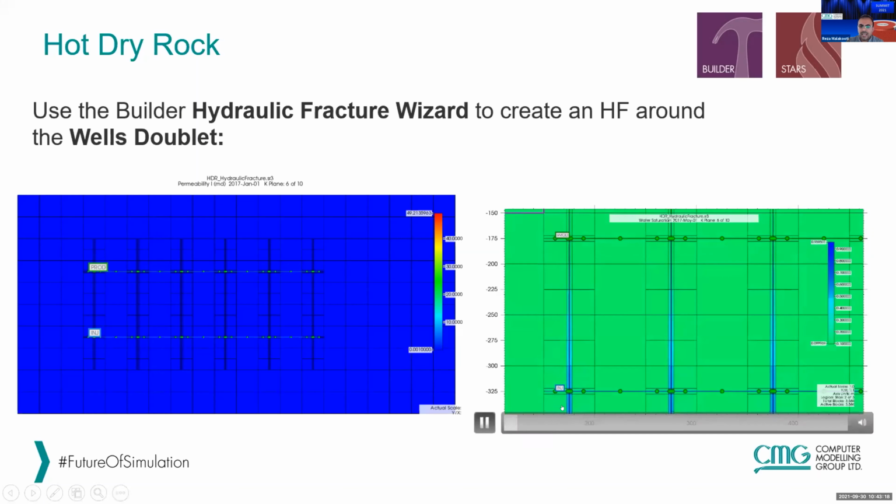In terms of details of modeling such a coupled GEM CoFlow model, because GEM does not have heat transfer modeling in the wellbore like STARS, we need to use the hydraulic fracturing wizard to represent the horizontal sections in GEM, where that channel or fracture would represent a lateral which would connect the injector to the producer.